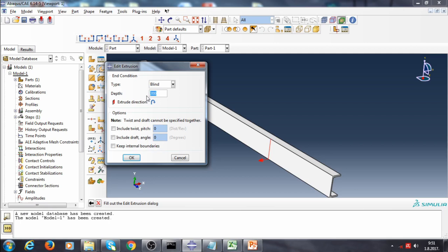I will not be showing you how to calculate the distance of the shear center from the web, but you can do it in Abaqus. You can maybe find some data on the internet about geometrical characteristics of your cross section, but I think the most accurate way is to use Abaqus to calculate the distance of your shear center from the web.